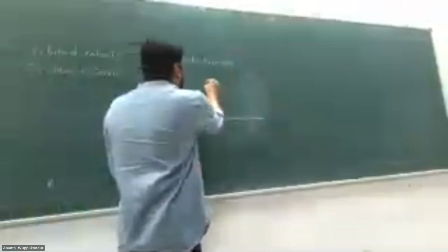And what about cohesive sediment? So these are, let's say, sand particles where there is no cohesion. Now, what about cohesive particles which are very fine? So if the particles are very fine, what about the weight of the particle? So the weight of the particle is going to be less. So if the weight of the particle is less, then it can get easily suspended in the water column. So the fine particles are going to move within the water column. So these are called suspended load.